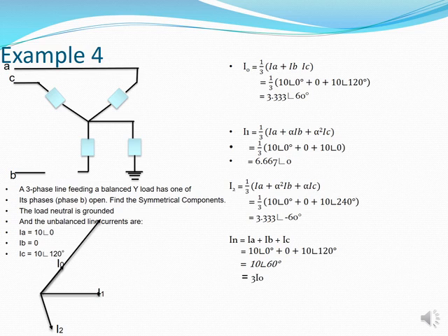So I know that my IN is the IA, IB, and IC together, which really is just 3 times my I0. I can just go to my I0 and multiply that by 3 and get my answer, whereas I also could have added those 3 things together to get my answer. It just proves that this actually works as is.